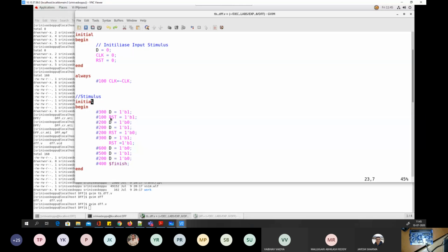One thing to note is that this statement started executing only at 300 time units from the beginning. Do not confuse that it will start executing at 100. This is a kind of blocking statement. Earlier you have seen the less-than-or-equal symbol, which is non-blocking; these are blocking statements.